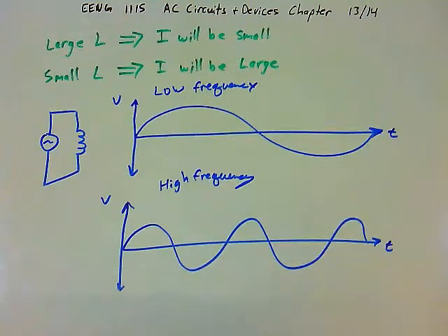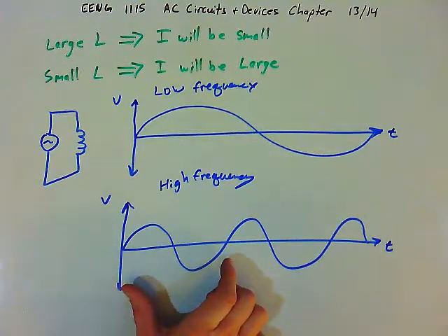And so let's think again about, well, how does that affect the current? Remember that when the inductance is large, the current rises slowly, and when the inductance is small, the current rises more quickly. Regardless of whether the inductor is large or small, though, the current does not rise instantaneously. It takes time. And so that's what we're talking about here, is the amount of time.